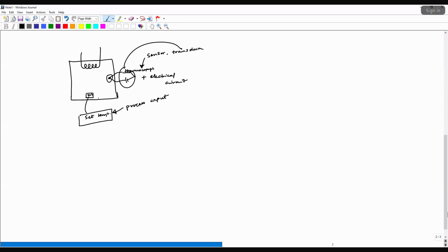And let's say, as I said, you have set 70 degrees, and when it reaches 75 degrees, then you must have a signal conditioning or control stage. Depending on the temperature, let's say initially it is 25 degrees and then it reaches 75 degrees centigrade, then the signal should be fed back to this heater, right? It says cut off because the temperature has exceeded the set temperature, right?